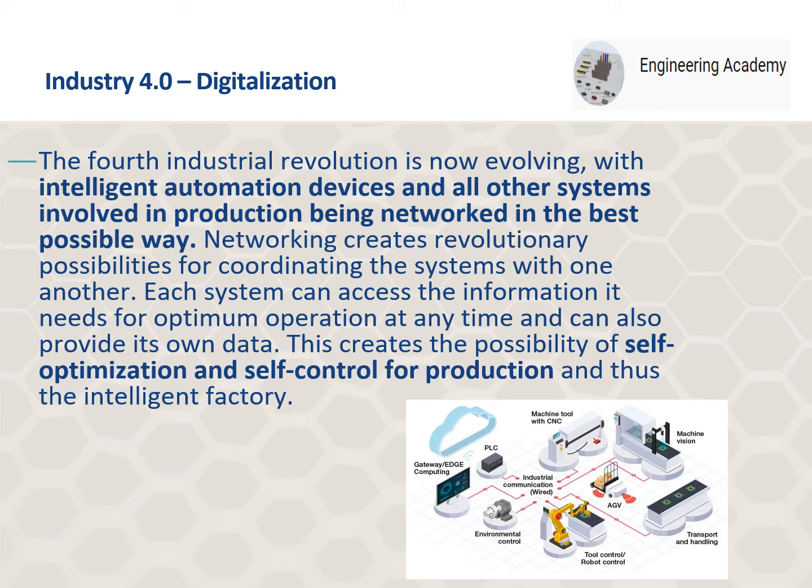We're also looking at how to design the factory. From previous examples I've worked with, I worked with a company where we worked out that the materials to make a car brake pad would come into stores, and it would literally travel 2 miles through the factory before it was completed. So by getting all that data, we could reduce the flow of parts through the factory through discrete event simulation.